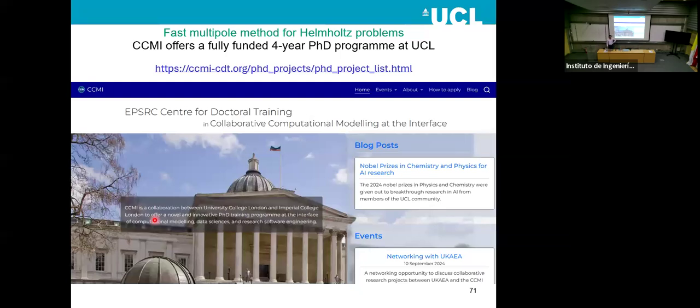So we've used adaptive meshes; we've had to do it to solve very large problems. In essence, if you refine the grid close to where the field is located and coarsen the grid elsewhere, you actually get some pretty reasonable results. You could get away with two elements per wavelength in some parts of the grid for large domains.